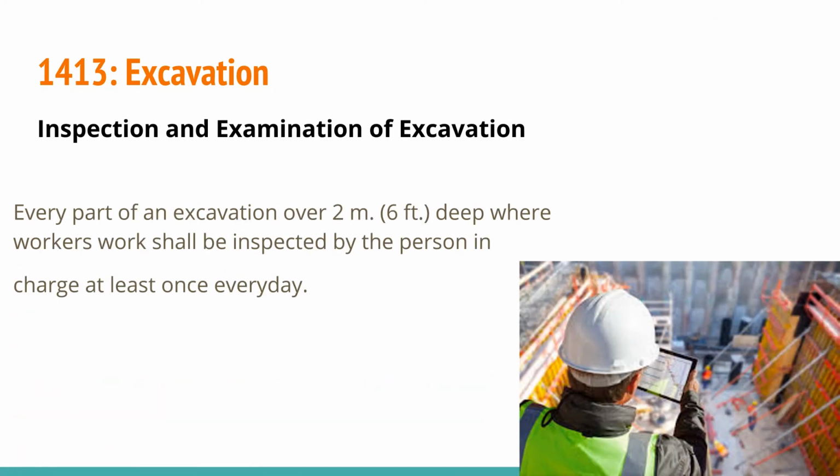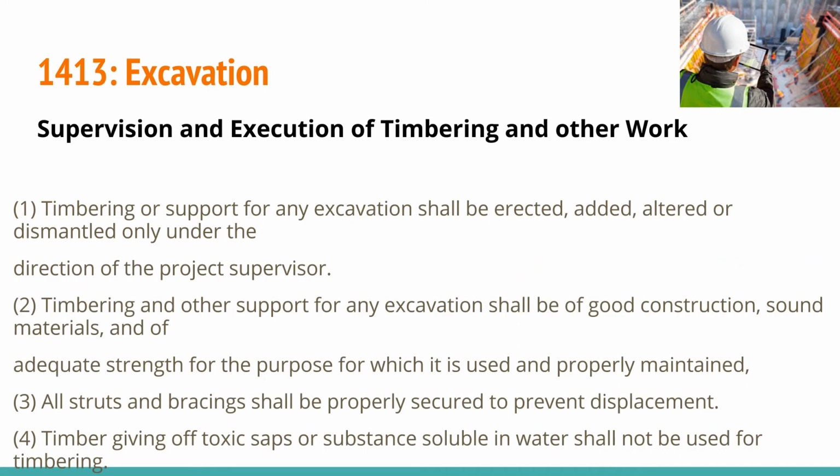So the inspection and examination of excavation is such that every part of an excavation over 2 meters or 6 feet deep, workers shall be inspected by the person in charge at least once every day. So during the supervision and execution of timbering and other work, timbering or support for any excavation shall be erected, added, altered, or dismantled only under the direction of the project supervisor.